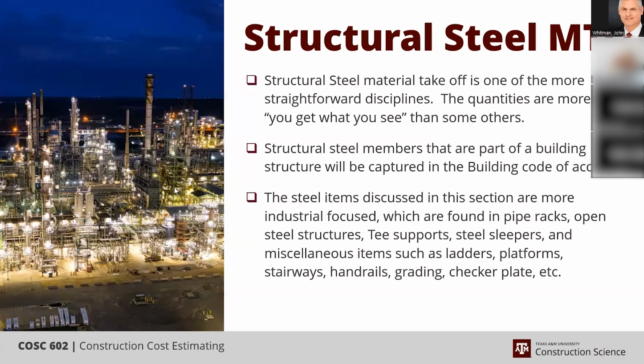So, towers, as you can see here, stand alone. And of course, this is a stack, and I think those 2 are stacks, but that's a column and that's a column. So you can see that towers and columns can stand alone without a structure around them if they're designed properly. But often, if there's a lot of pipe that's hanging off the tower or column that needs additional support, either the column has to be designed to provide that extra support, or the open structure will help with it.